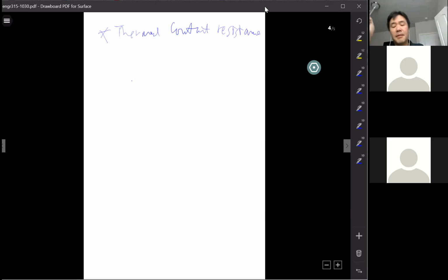So here we're talking about the fin, right? You install a fin to increase heat transfer. When you attach it to some structure, there's something in contact, either glue or whatever material. Or sometimes you're not in perfect contact on the surface, then you have gaps, air trapped in between the contact.